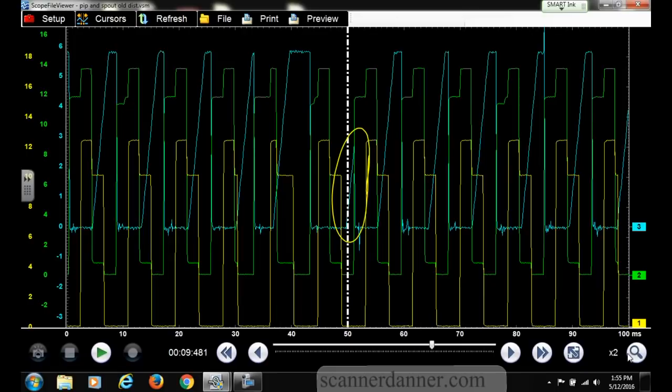What cylinder is that? Is my point that I wanted you guys to get before we leave. Didn't you say it was 2? Yeah, my number one trigger is right here. This is the skinnier PIP signal. So there's your fatter ones. There's your skinny one. This is number 1. And in the firing order, this would be then the number 5. This is the number, was it 4? And then this one's the number 2. And so that's the one that's affecting that. Is the number 2 cylinder.